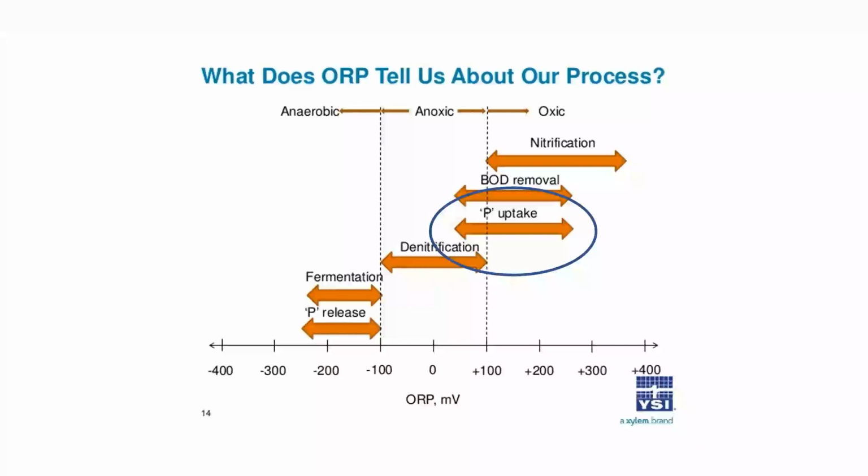But they are making sure the pH can get good ammonia removal at a slightly lower pH than phosphorus removal. So the magic number is 6.8. Like to see it at 7. If you have a pH of 7 in your aeration tank all the time, and you're getting ammonia removal, you've got a good environment for phosphorus removal.